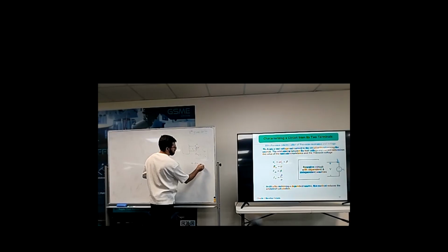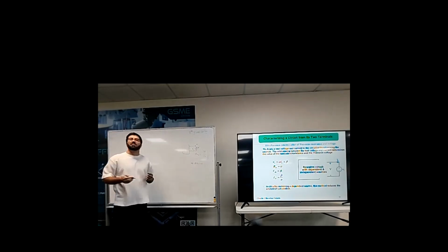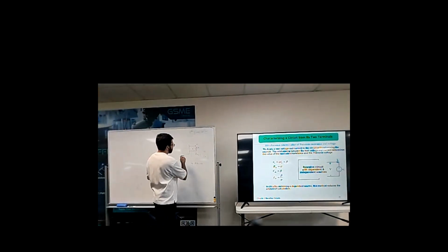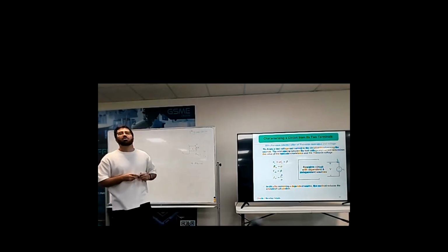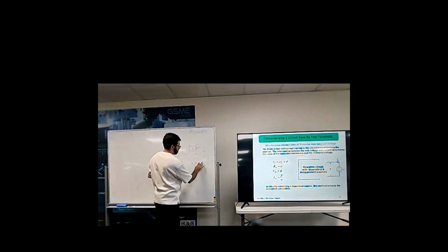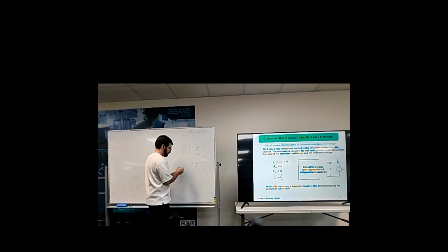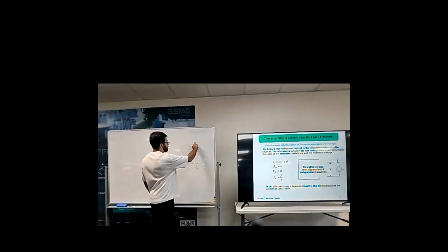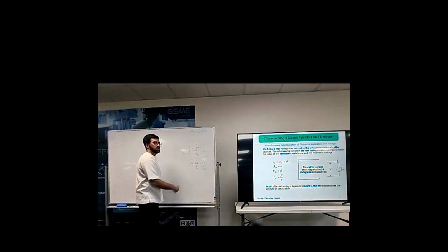It was zero here. Why? Because this is effect of independent sources. So if you don't set the independent sources to zero, that means we have a constant here, which is equal to Thevenin voltage. And this is R Thevenin. That means if you apply VT and find the IT, you can find the whole together.